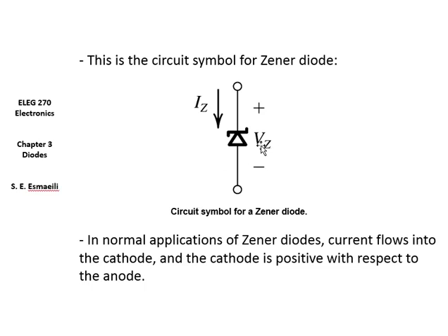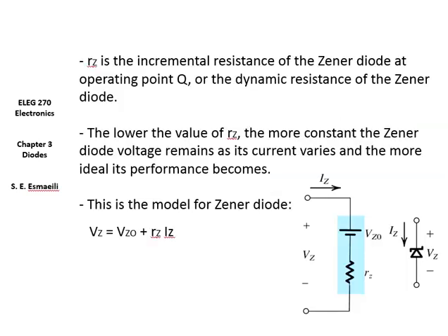But the Zener diode, no, we can even use the Zener diode in the backward bias, so not only in the forward bias. The forward bias of the Zener diode is the same, like 0.7. The backward bias of the Zener diode will also give us the VZ that is actually applicable in different circuits, and can make voltage regulators, these things with it. So make sure that you understand the operation of the Zener diode in lecture note 17.